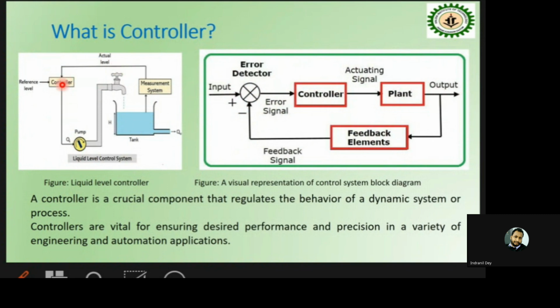So the controller will get an error of 10 minus 7, that is 3 centimeters, if 7 centimeters is the desired value. You can see the plant has a positive error of 3 centimeters, where our reference value is 7 and the actual height at that instant is 10.